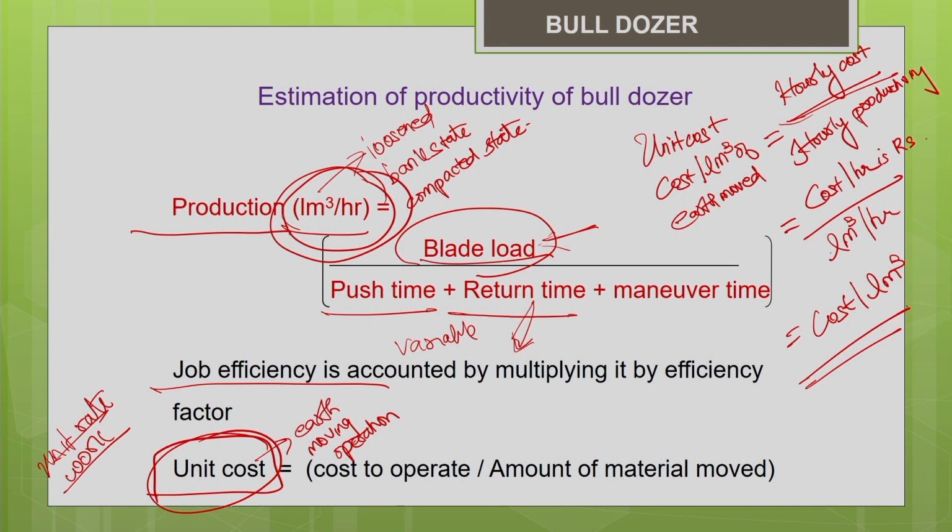This is the data which we will be commonly using. This will be a part of what you quote in your bid. The unit cost of production of this activity forms a part of the unit cost you generally quote in your unit rate contract bidding. So, the estimation of this is very important, and you should estimate it as accurately as possible, so that you can properly plan for your bidding.